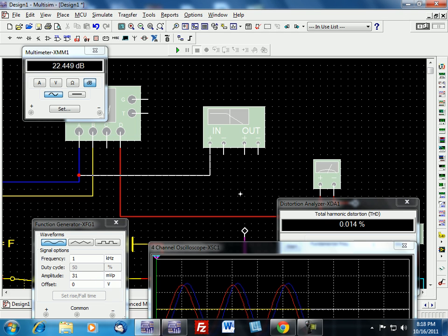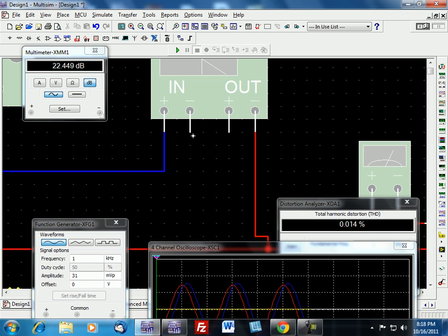This is an instrument that we use to determine if the amplifier has good frequency response. And we're going to do a sweep from 20 to 20,000 cycles. Audio frequency is designed around 20 to 20,000 cycles flat.